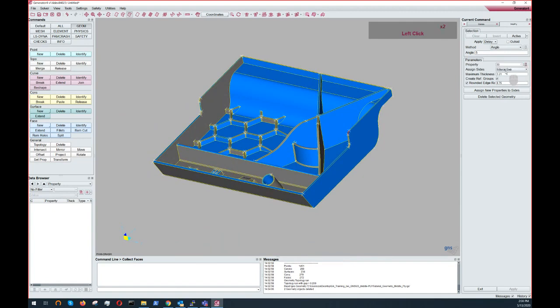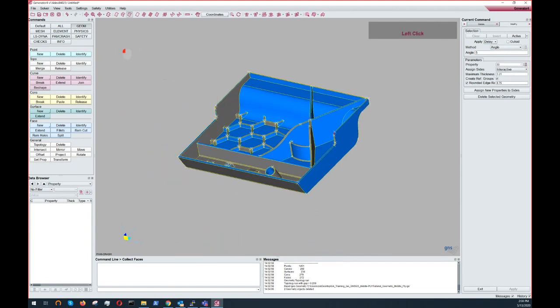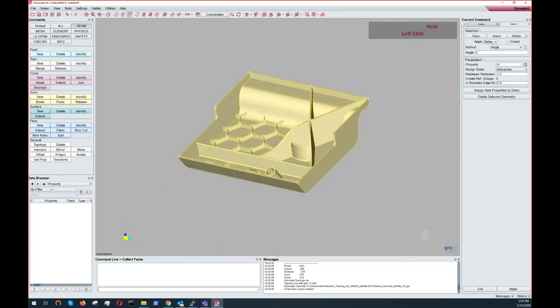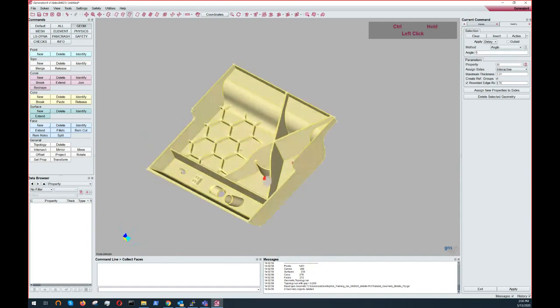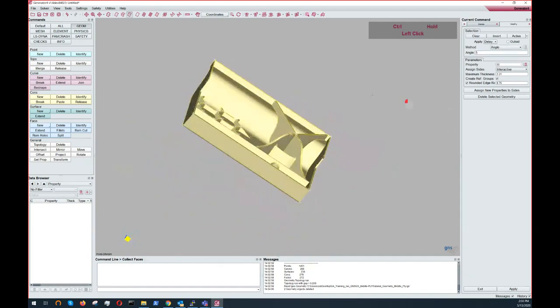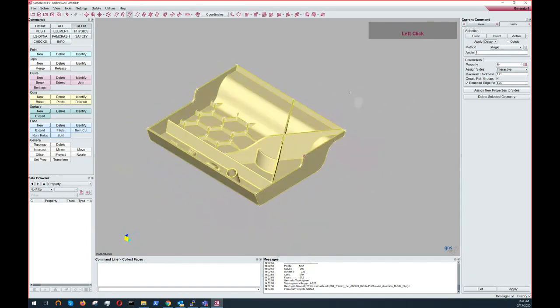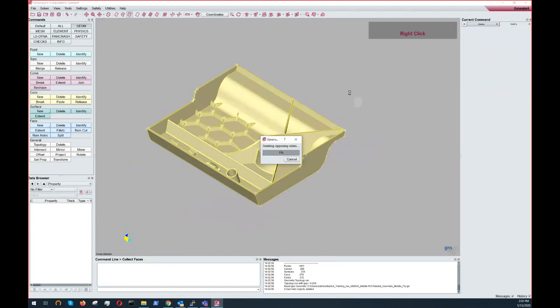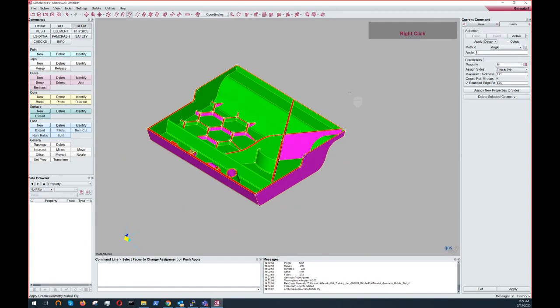It's the interactive one. There you select all the faces just by drawing a mouse box, or just clicking here on active. You can get everything selected. Then you can confirm, okay, everything is selected, it's okay. Right mouse for confirming. And then generator evaluates this part. And instead of automatically creating the middle ply, it lets you check what he thinks.